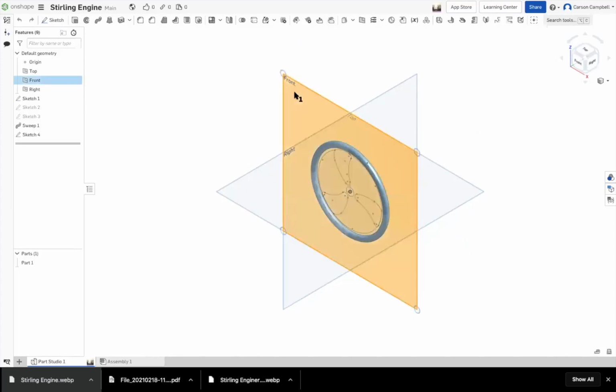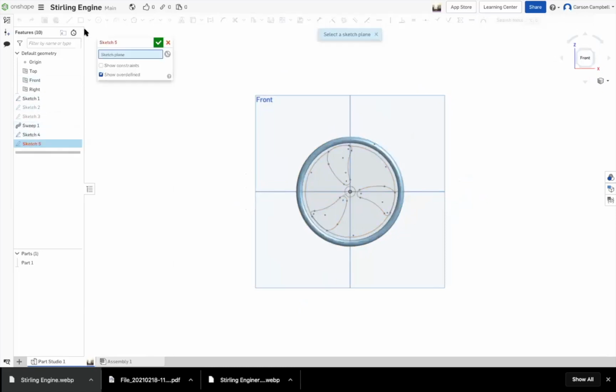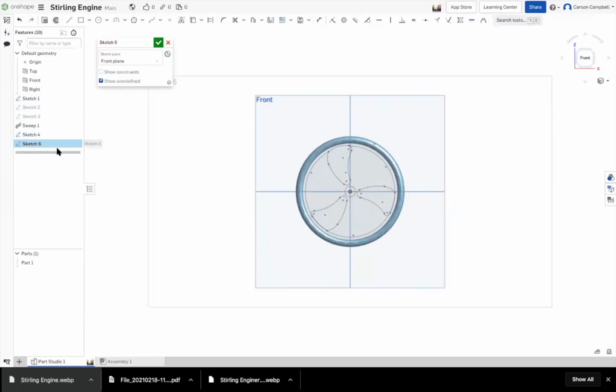One of the problems that you're having is that images go in sketches. So you need to, and I have a sketch dedicated to an image. I don't have geometry in the sketch. So you need to create, there you go, create it. Now go up to the drop down menu that has DXF over to the right, okay, over to the left. There it is.